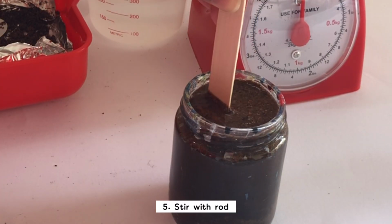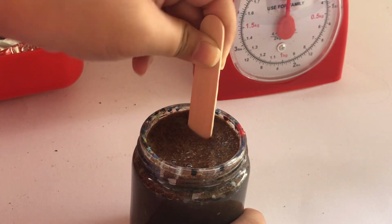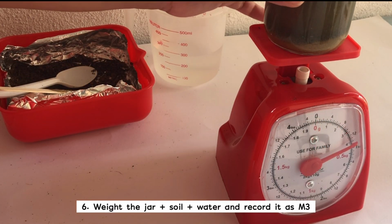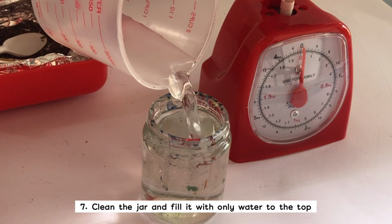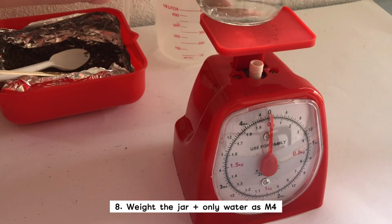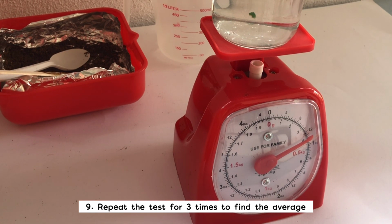Next, by using the rod, stir the soil and water together. Then weigh the jar plus soil plus water and record it as M3. Clean the jar and fill it with only water to the top, and then weigh the jar plus only water as M4, and repeat the test 3 times to find the average.